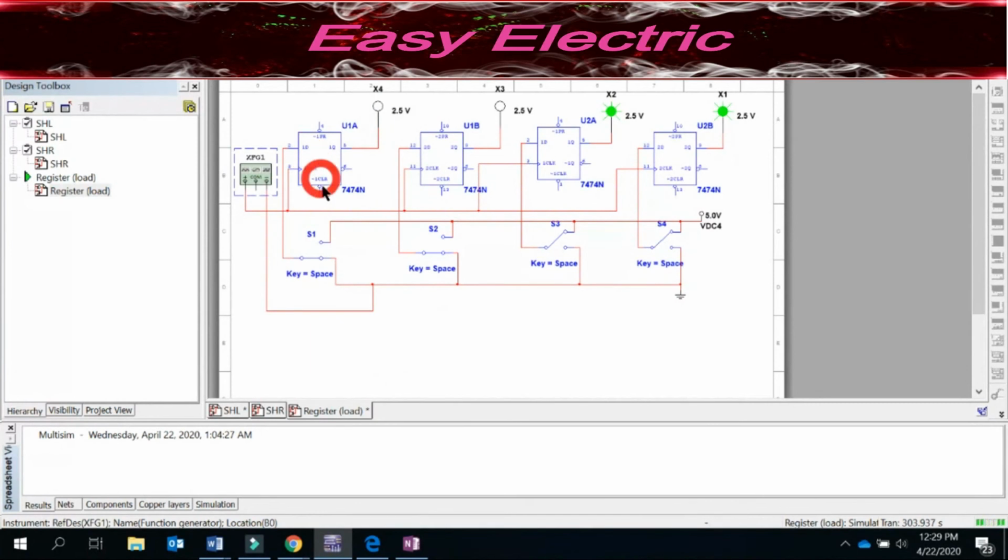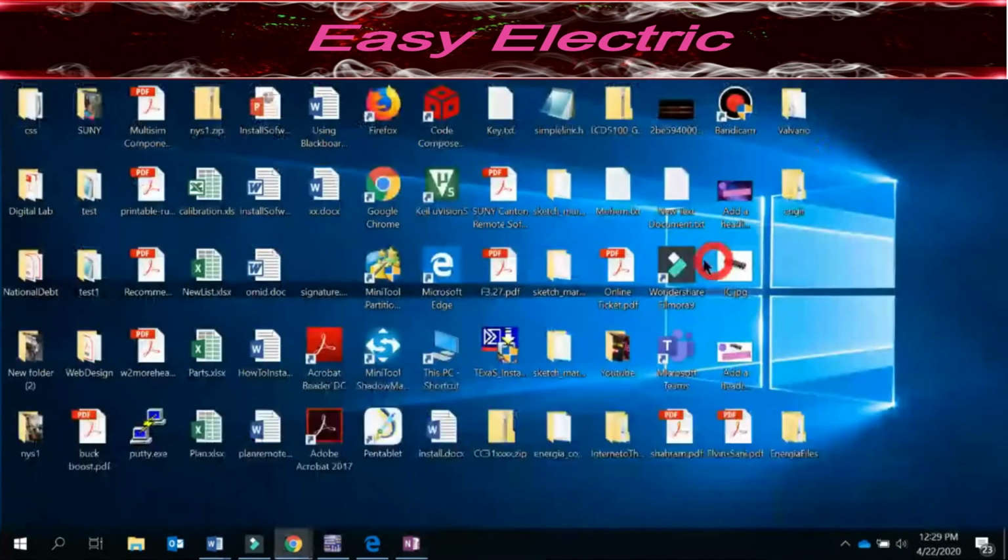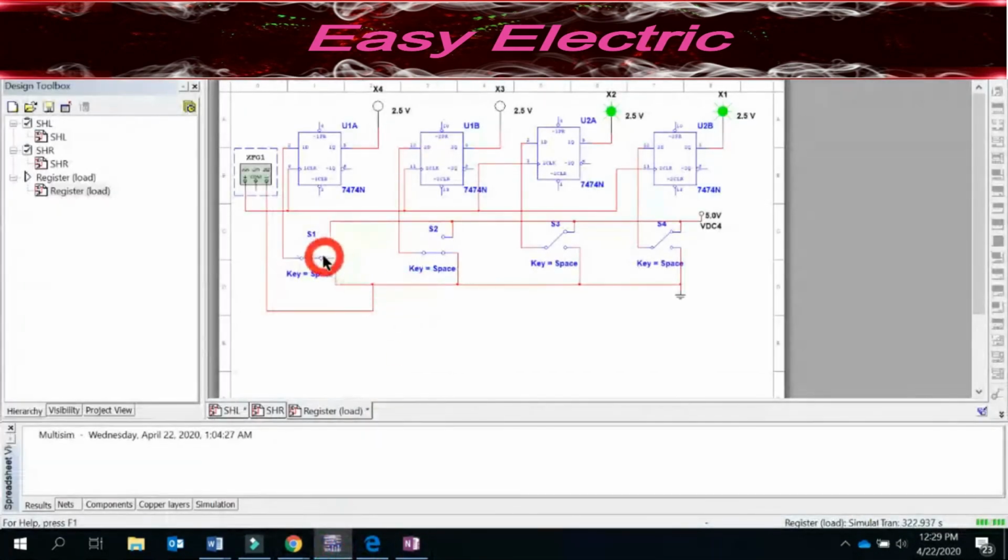That's actually cool. So see, right now this is 0, this is 0, right? So whenever I put this on, it's not going to be immediately on because it needs to wait 10 seconds to see the second rising edge, then update the value, right? So that's what happened here. I'm on 0 right now. I'm changing to the 1. It's not 1 yet. So it should take 10 seconds. Yeah, after 10 seconds, it's able to see the change and update that value.